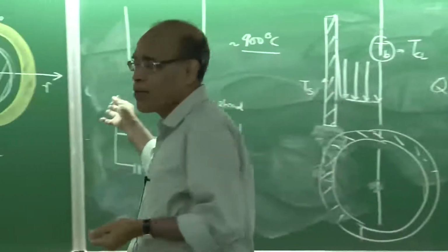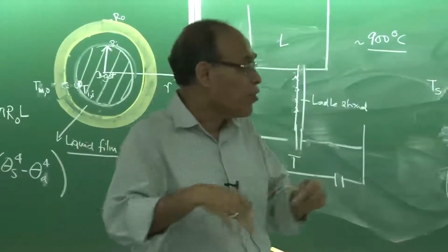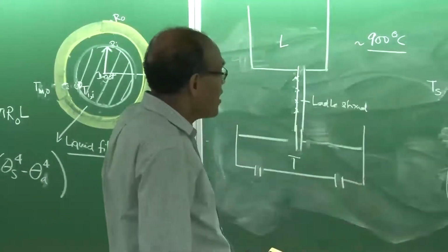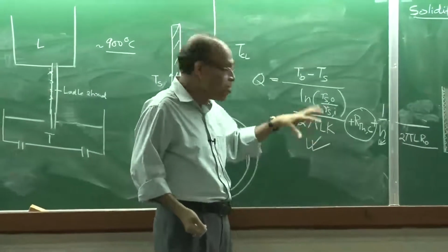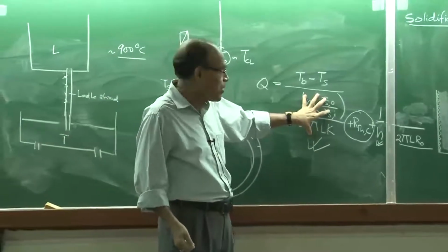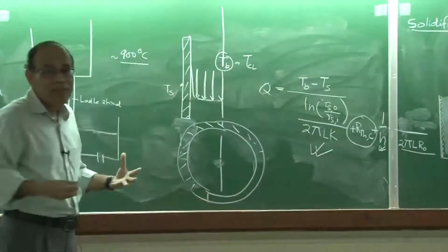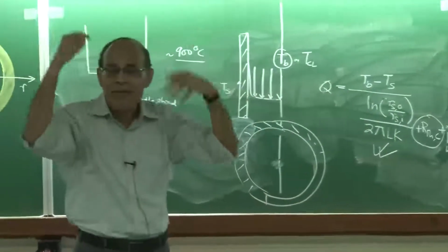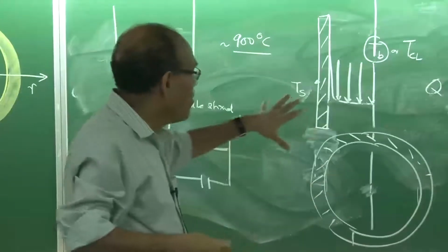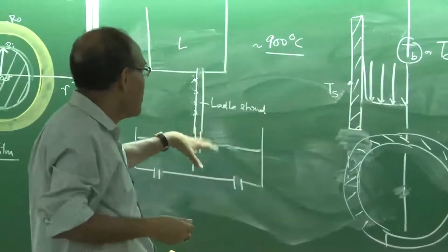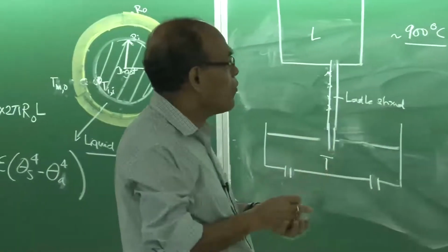And this has been a very common practice among researchers like us, to use heat transfer fundamentals. And as you can see here, where did I get this equation? From the fundamental law of heat conduction in cylindrical polar coordinates. Okay? So whatever you learn, even if you may be doing some advanced level calculations, the starting point will be the conduction theories, which will be applied in order to deal with certain aspects of heat flow during the solidification process itself.